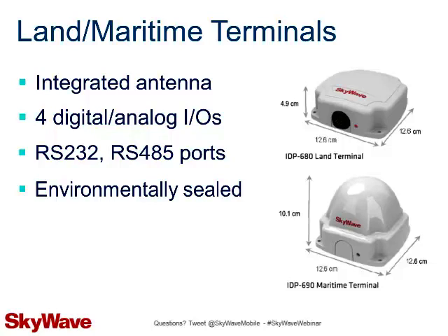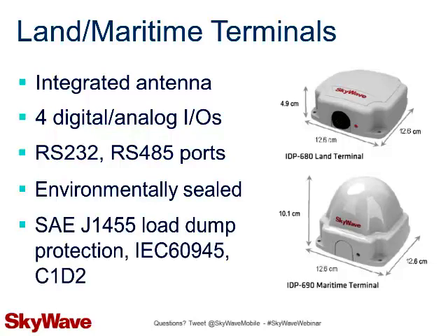And finally, it already has been certified by industry for a number of applications like SAE J1455 for load dump protection for the transportation market, IEC 60945 to ensure that the terminal does not interfere with GPS navigation equipment on maritime vessels, and Class 1 Division 2 or C1D2 for use in hazardous locations for many oil and gas or